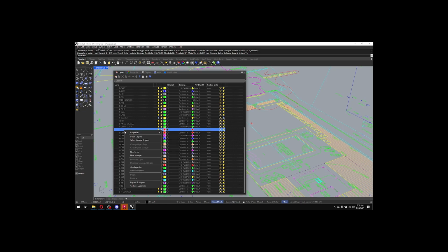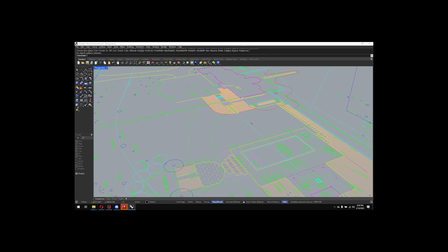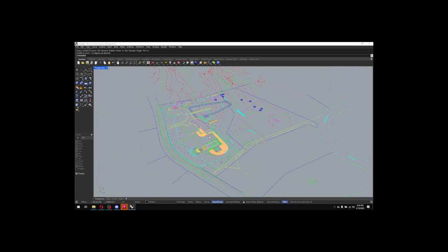This also applies to your non-work sessioned objects, but I can select those objects on that layer, go back in here. Let's just close this guy, Z enter, S enter, and it'll zoom in on all of those that are selected. So if you get a little lost, just grab something in one of your layers and zoom in on it, and it'll kind of recenter your camera.